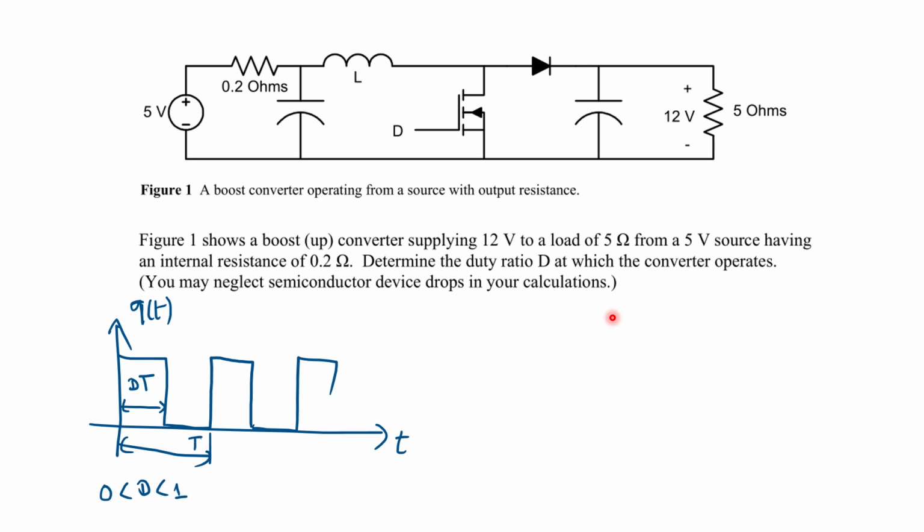Like I explained earlier, for a buck converter or boost converter, the process to find a relationship between V1 and V2 is to first plot the graph of voltage at the inductor, and then use the property of zero average voltage. Then you can find a relationship between V1, V2 and duty cycle, right? So in the ideal case of buck and boost converter, you just use one property, and if you know the duty cycle, then you can easily calculate the voltage at the load.